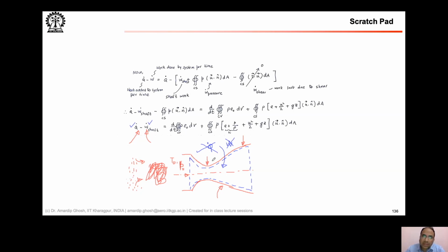I mean, see, the thing is, in the real case, some combustion is going to happen. So you will learn about things like frozen flow, equilibrium flow, non-equilibrium flow, etc. But at this point, we will assume that the combustion has happened. My gaseous charge has reached a static temperature, stagnation temperature, and stagnation pressure of T naught and P naught. And now I am expanding through the nozzle where there is no Q dot, there is no W dot.